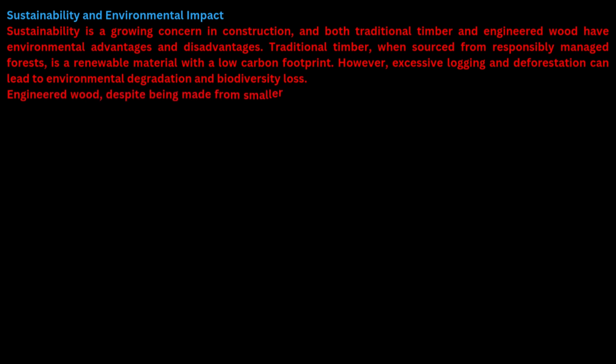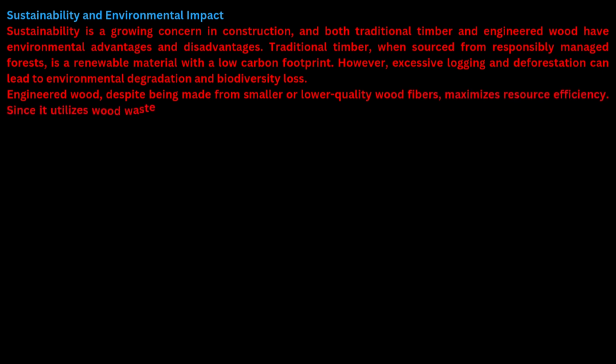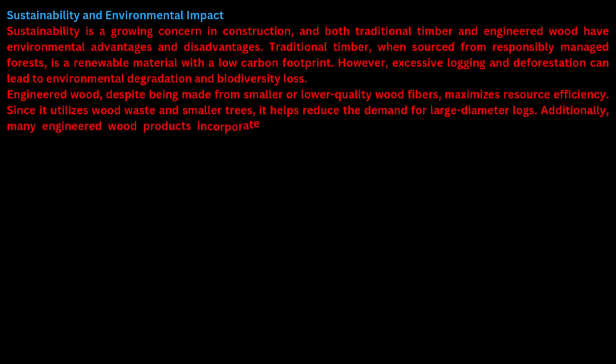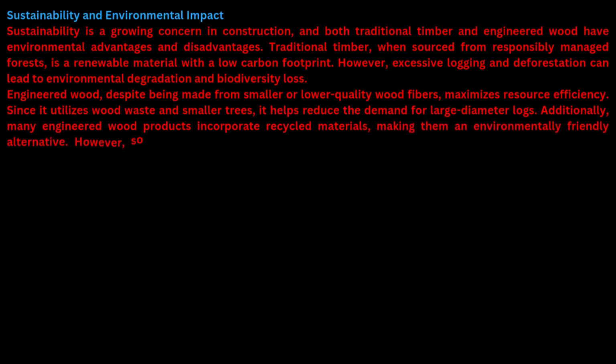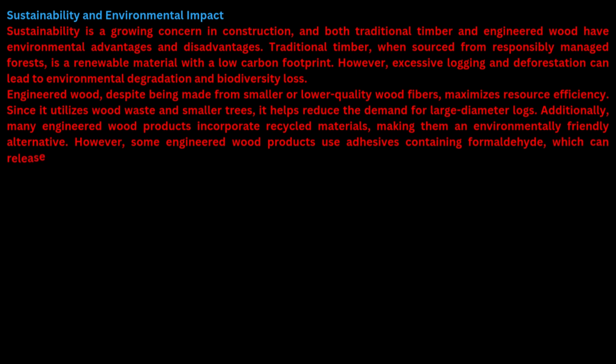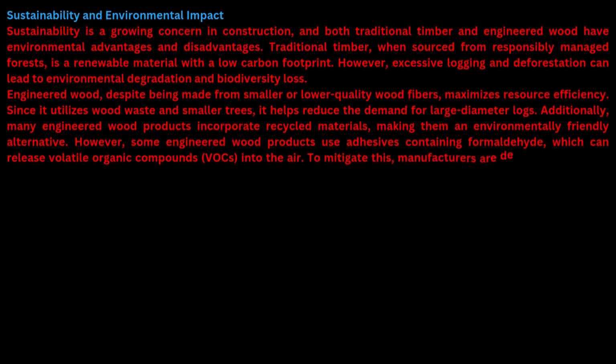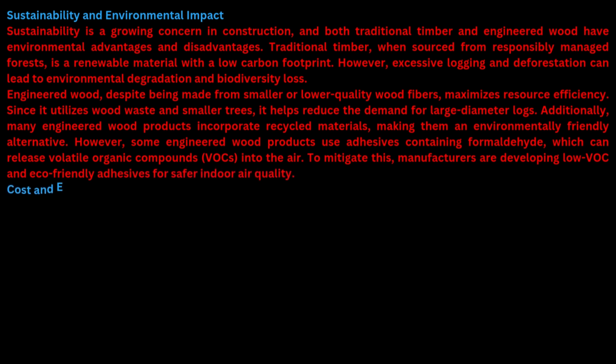Engineered wood, despite being made from smaller or lower quality wood fibers, maximizes resource efficiency. Since it utilizes wood waste and smaller trees, it helps reduce the demand for large diameter logs. Additionally, many engineered wood products incorporate recycled materials, making them an environmentally friendly alternative. However, some engineered wood products use adhesives containing formaldehyde, which can release volatile organic compounds, VOCs, into the air. To mitigate this, manufacturers are developing low VOC and eco-friendly adhesives for safer indoor air quality.